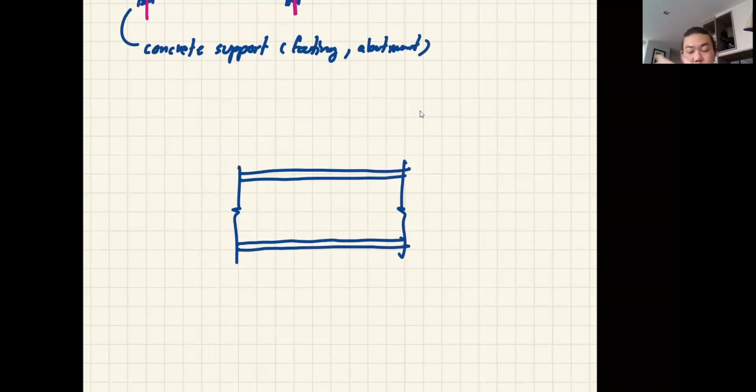We always draw the point load on paper as an arrow on a dot. But in the real world, your point load must come with dimension. If your beam supports some vertical member coming down with a load, it has to be attached to your beam by some kind of plate. So this plate becomes the area where your load acts. It is a very small area, that's why we call it point load. But in fact the load comes with some dimension, though it's not large. It's not on the entire beam.